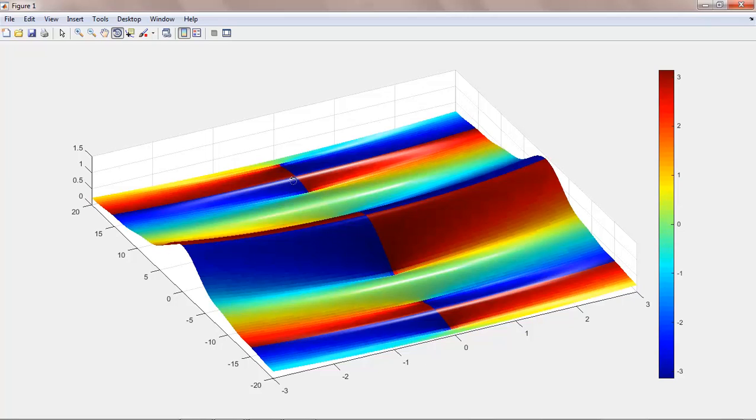Now, we have the value of X of s is complex. What I'm plotting in this plot is the magnitude of X of s, so the absolute value. But I'm using the color to plot the phase. Any complex number, we could do magnitude and phase. So here's the color chart for the phase: 0 phase, up to pi, and to negative pi. Of course, it wraps around. So these parts that look discontinuous, it looks like the phase jumps discontinuously, but that's not really discontinuous. You're just going around. You're getting greater than pi, and that makes you the same as a negative value.